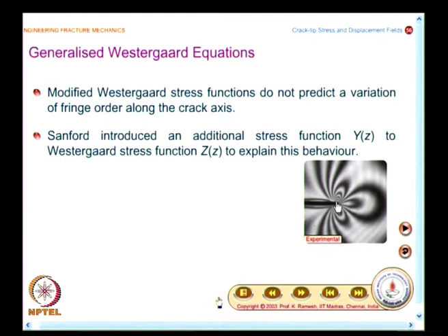emphasis, the solution we got from the Westergaard stress function had the maximum shear stress also 0, as did the modification by Tada, Paris and Irwin. We did not want it, we only specified tau xy to be 0.